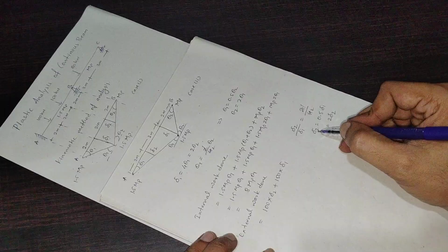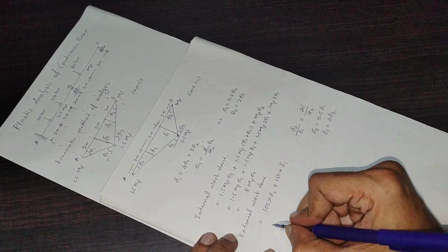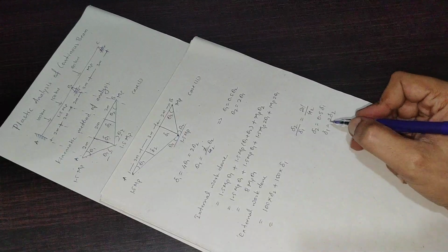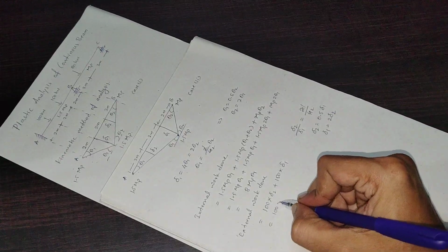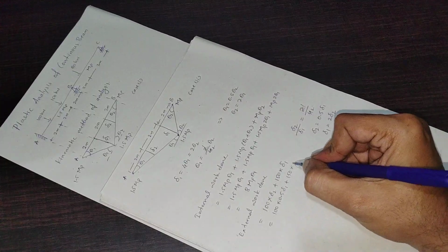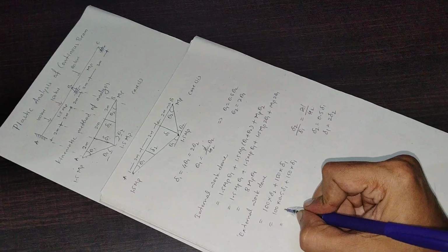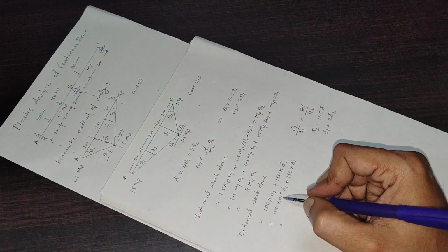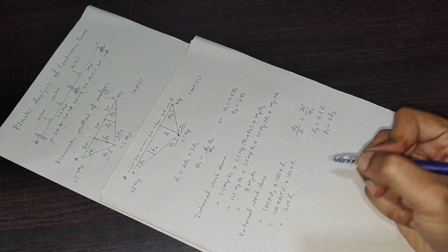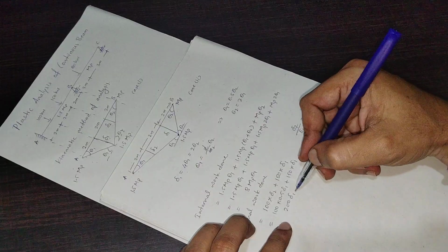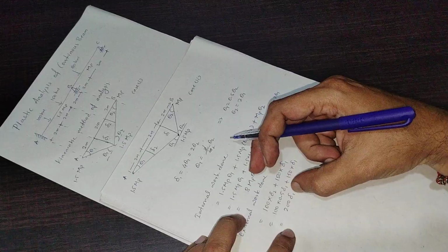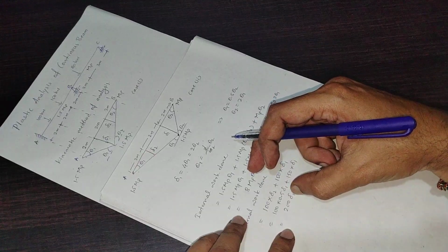I substitute either delta 2 or delta 1 in the external work done. So I will substitute delta 2 as 0.5 delta 1: 100 times 0.5 delta 1 plus 150 delta 1. So it is 50 plus 150, 200 delta 1. Now this delta 1 is to be substituted in terms of theta 1, because that is how I can equate the internal work done and the external work done.